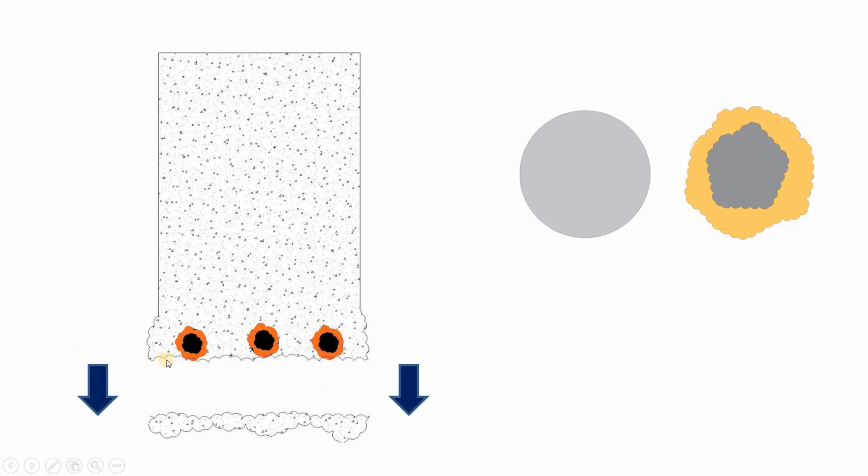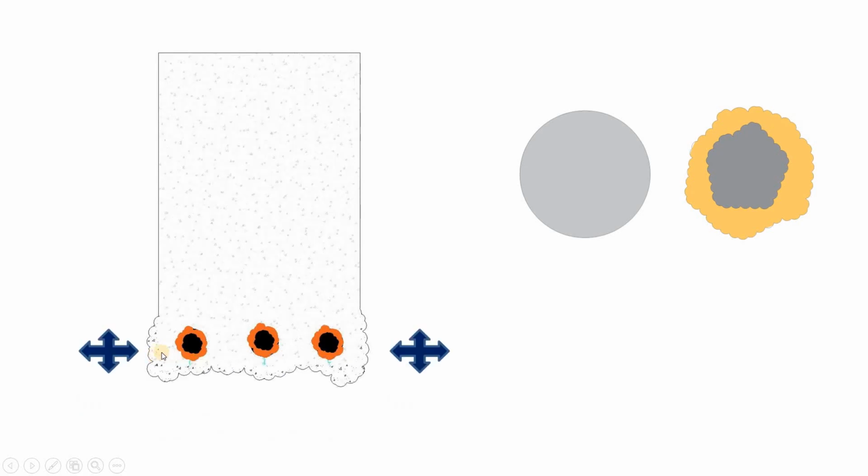This compressive force gets balanced at the top because more concrete is there. But in other places, on the sideways, the concrete will get bulged like this. At some point of time, where the stresses are very high is where the concrete area is very less. So there will be a chance of cracking at the place where stresses are very high. The concrete will spall like this because at this place the concrete area is very less. So here cracks will develop and the concrete will spall down like this.